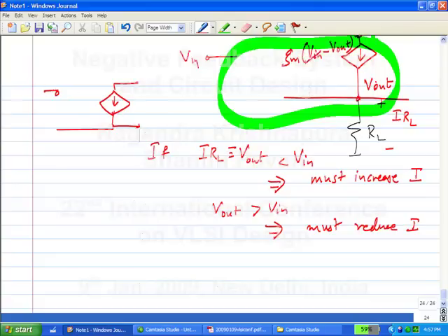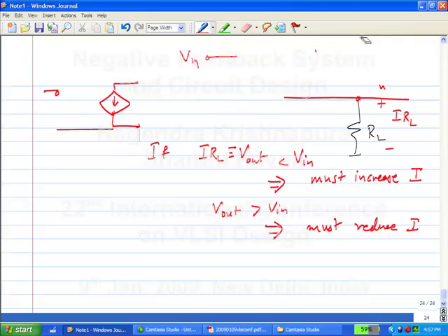So you can identify the transistor. This is the transistor. So where does the gate go? V in. The source goes here, the drain goes to ground. Alright. So do you recognize this incremental picture? What is this? The common source stage.